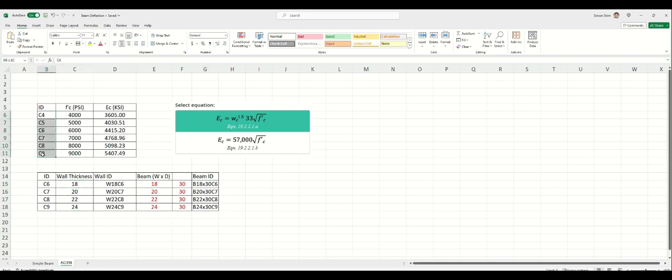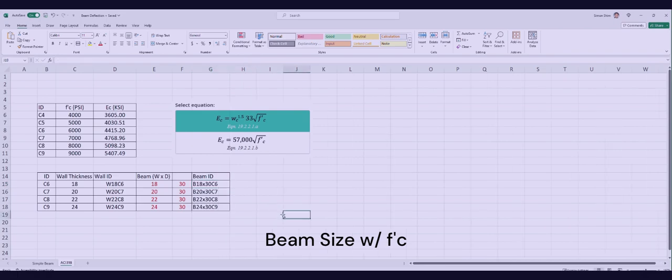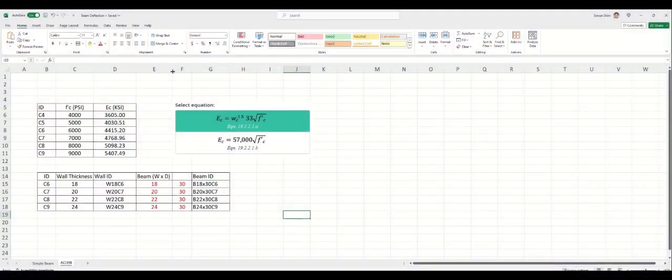Maybe we can have material names, wall thickness names, and beam names, using their thickness and concrete strengths, width and depth, so that we can easily control all the members of our ETABS model.